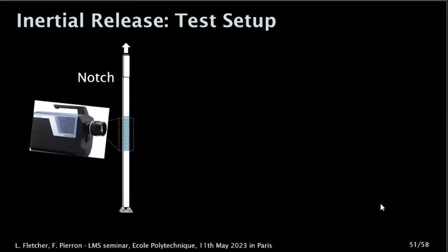So here the idea is that we are going to use a fracture to generate a release wave to load the specimen at high rates. So you can see here, this is the long specimen, and the specimen has a notch here. So you put that in a tensile machine, you load it up, and at a certain point, it will fracture because you have a stress concentration. And when it fractures, what you have is a compression release wave that travels down the specimen. And if we can capture that with a camera, then we basically have built a very cheap impact machine.